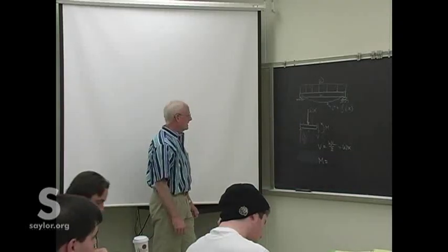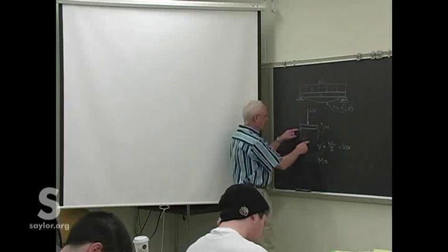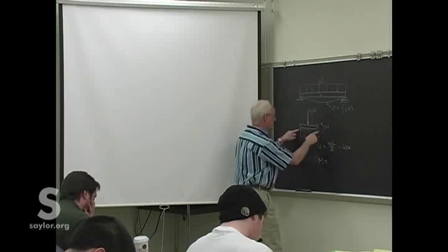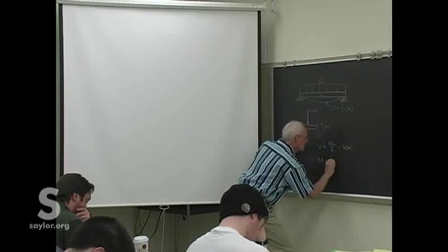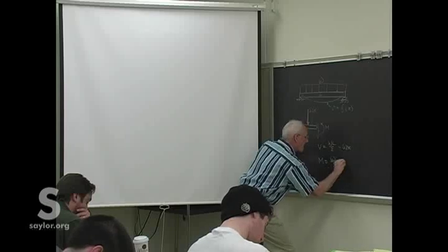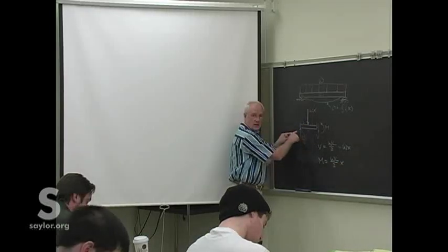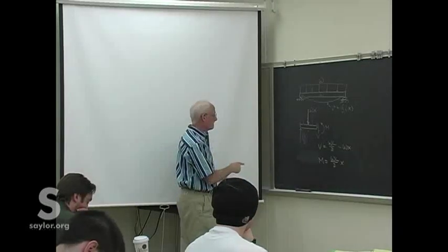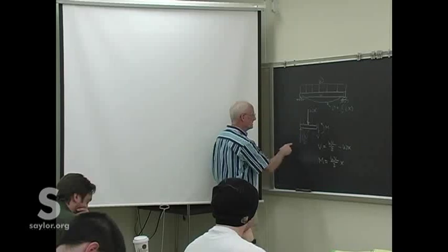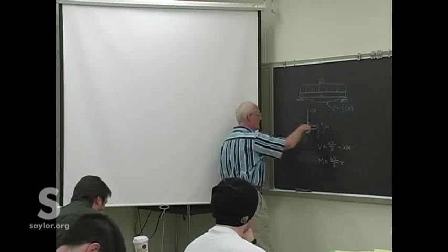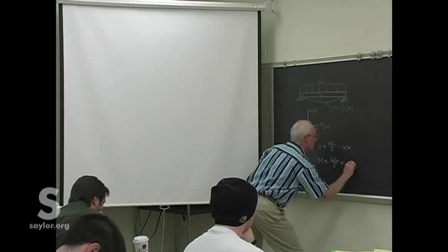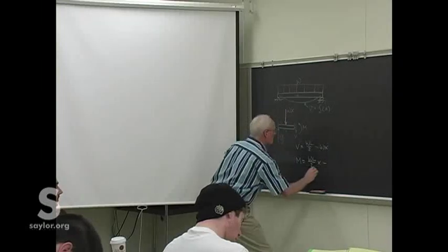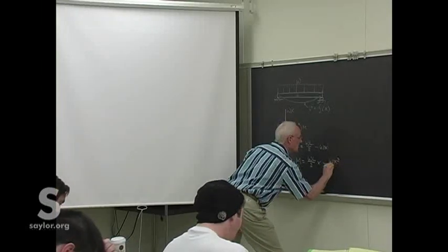And the moment must be WL over 2 times x. That's the moment due to the reaction. Then we have the moment due to the load, which is in the other direction. So that's Wx squared over 2.